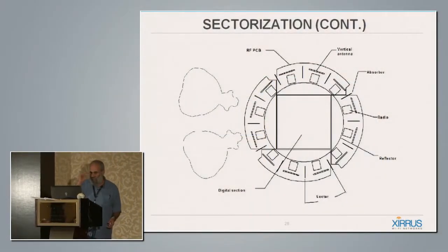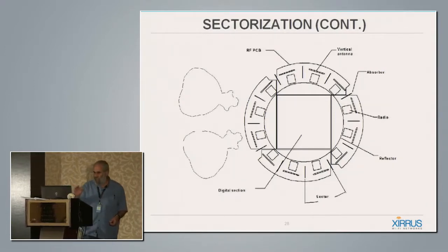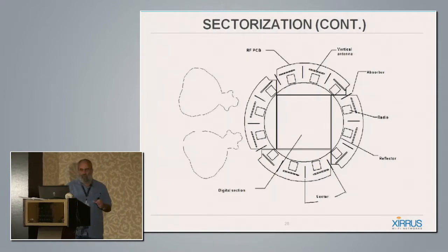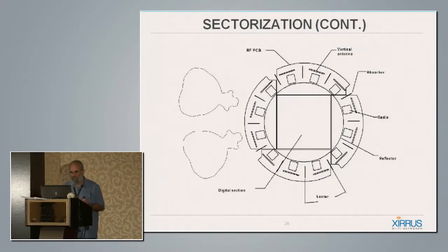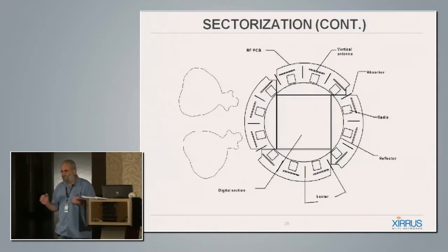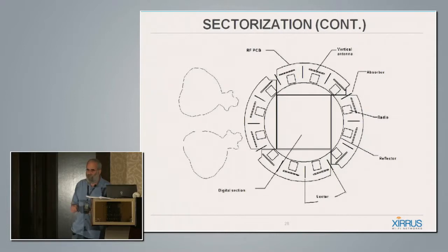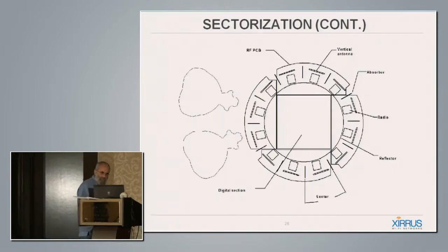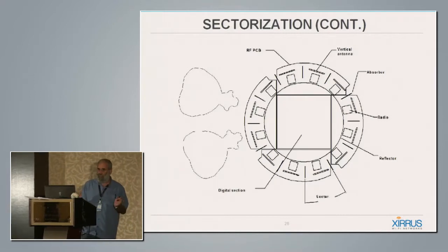This is one of the old designs at Xerox, and you can see that always you have a radio, in our case at least, and an antenna, and it's broken into sectors, and in between the sectors, at that time, we used absorbing material that helps to minimize any splashes that are due to side lobes and unwanted radiation coming out of the antenna. So by adding those absorbers, you kind of control the isolation.